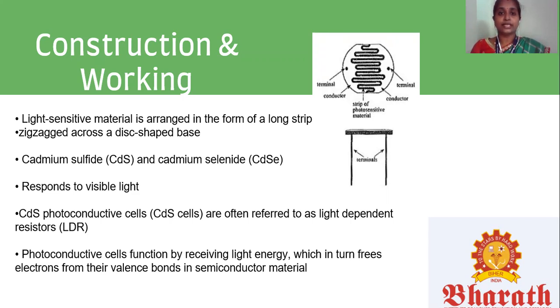For cadmium selenide, the response time is around 10 ms, while for cadmium sulfide it may be as long as 100 ms. Temperature sensitivity is another important difference between the two materials. There is a large change in the resistance of the cadmium selenide cell with changes in the ambient temperature, but the resistance of the cadmium sulfide remains relatively stable.